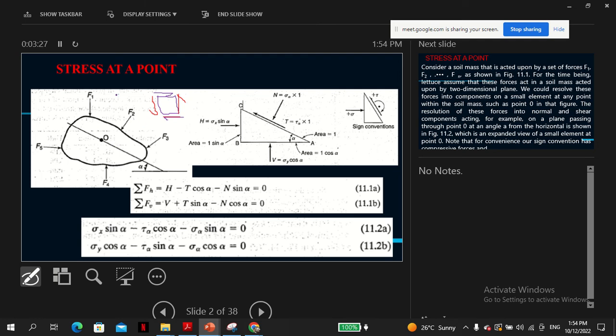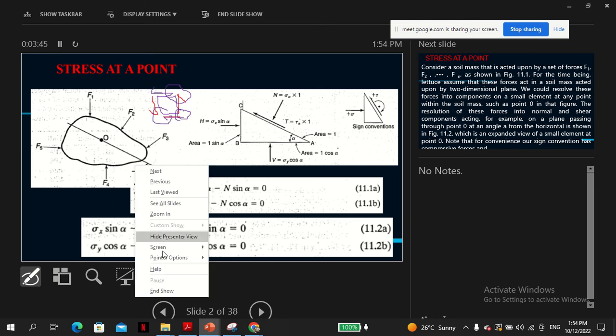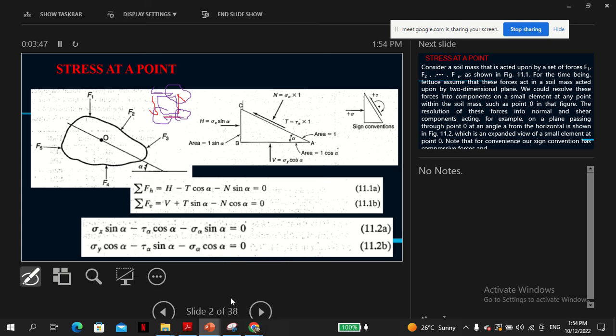Now maybe you may have known this from structural mechanics. The shear stresses either meet at a point. You can see these ones meet at a corner, either meet at a corner or depart from a corner. So these ones meet at a corner, these ones depart from a corner. Those are the characteristics of these shear stresses. That's just to make sure you understand what you're talking about.